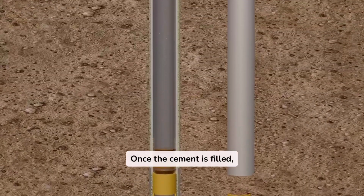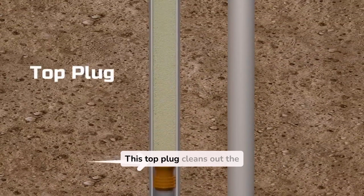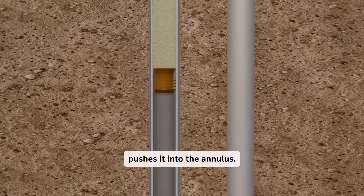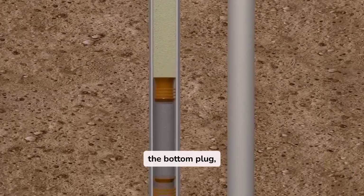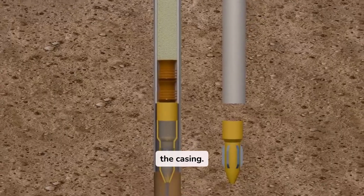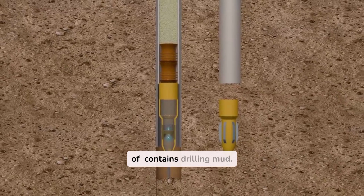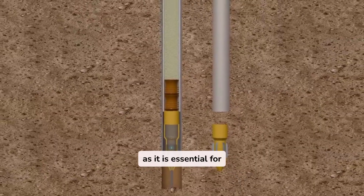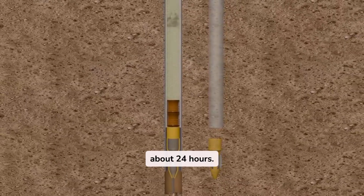Once the cement is filled, a top plug is inserted into the casing and pushed down using drilling mud. This top plug cleans out the remaining cement inside the casing and pushes it into the annulus. Finally, the top plug sits on top of the bottom plug, locking it securely and preventing the cement from flowing back into the casing. At this point, the annulus is filled with cement, and the inside of the casing contains drilling mud. The presence of drilling mud is not a problem, as it is essential for the drilling process. The cement is then left to set and harden for about 24 hours.